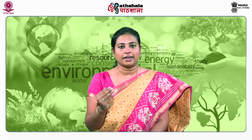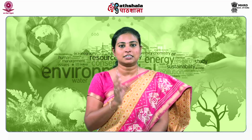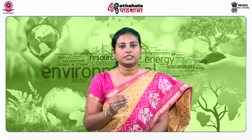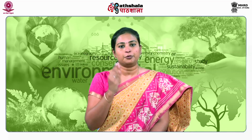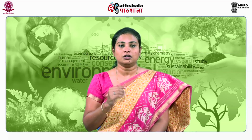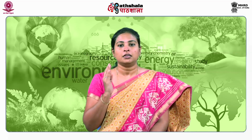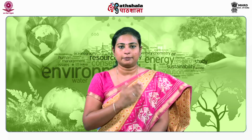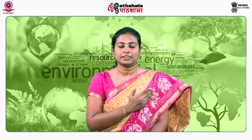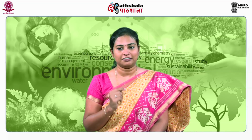Controlled dumping, on the other hand, is nothing but containing your waste in a safe disposal option such as a landfill. A landfill is an engineered structure which is provided with a liner, a cover and a proper way of dumping or loading waste within it. So, controlled dumping or landfills are always a safe option for disposal. In the previous modules, we have discussed both uncontrolled and controlled dumping, which you can refer to. In this module, we will be discussing landfill leachate management.